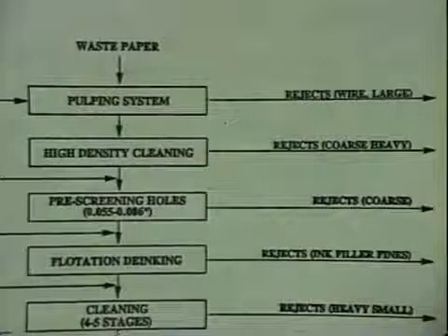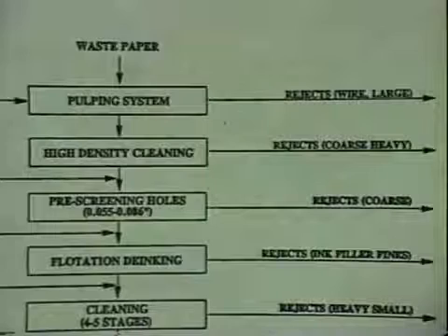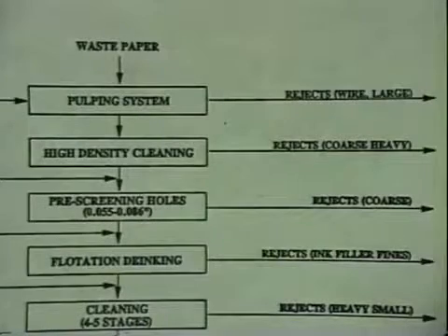First, let me actually talk about this. We're making recycled newsprint, okay, and we may have like a batch or continuous tub or drum pulper. And our strategy is going to be, first we're going to remove coarse contaminants, then we're going to remove smaller contaminants, do de-inking, and then third we're going to disperse unremoved contaminants, and we're going to maybe try and even remove those too. We may use bleaching to increase our brightness, and then problems with stickies might be an issue, especially if we add old magazine.